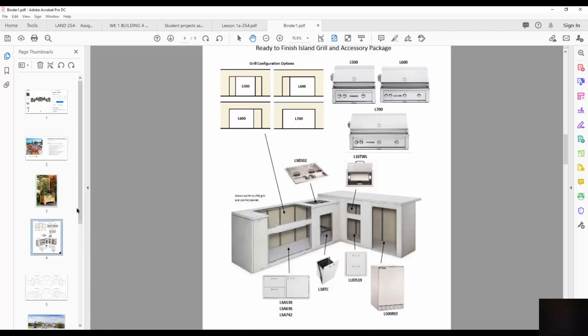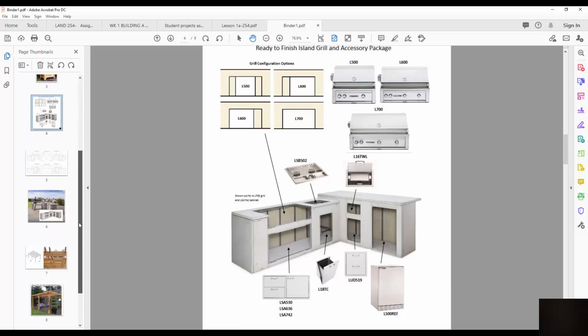And then for the kitchen, I'm expecting you to do some research to find out exactly how this is built. This is the style of kitchen cabinetry that we're going to have on the deck. So it'll be part of the deck component, and we can simply block underneath the deck to support it. So it is a light steel frame structure. It has a concrete board as a covering, and that's typical out here. So the concrete board doesn't deteriorate because of weather.